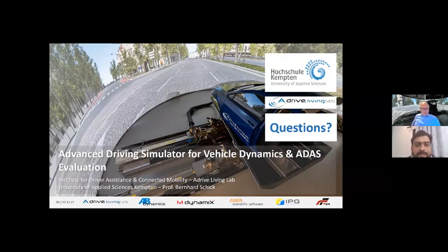I would say the 3D track model will be scanned. There are certain companies who can do that, and it will be scanned, and then transformed and formatted into so-called CRG, curve regular grid, and we can run on that. On one hand, we can integrate that in CarMaker, for example, a CRG can run with a tire on the CarMaker road, but we can also run on an F tire.